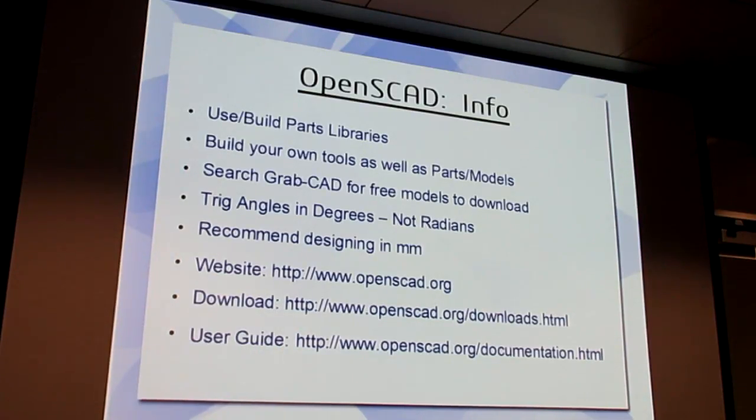So a module, there's a special magic parameter called children. So instead of having a module that contains parts, you just put this magic value children. Maybe the rest of that is a bunch of translates. Maybe there's some parameters that you're calculating. And I can use my module as if it was a translate function, put it in front of other objects and have it apply whatever transformations it has to the objects that I make its children by just putting them next to it. So usually you can build libraries of tools.